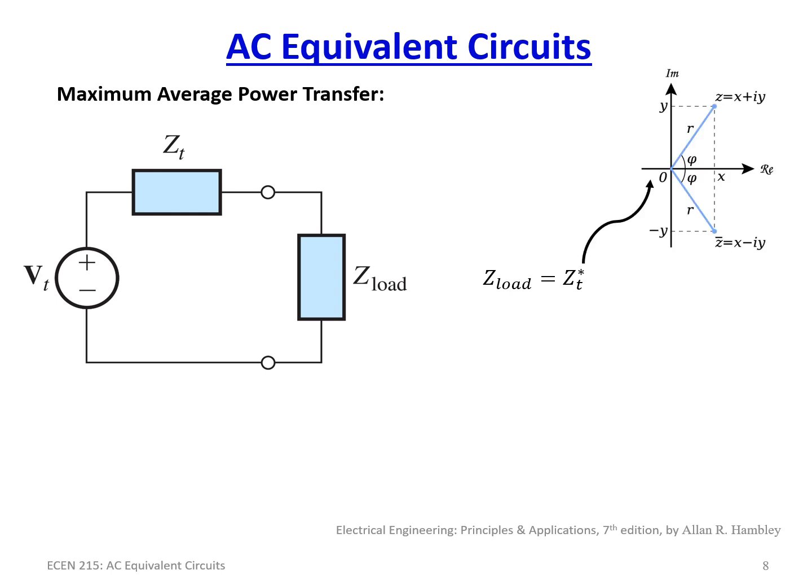And just as a refresher, the conjugate is where you flip the sign of the imaginary term. So if ZT was 5 plus 6j ohms, then the conjugate would be 5 minus 6j ohms. It's the same real resistance, you're just flipping the imaginary component. It also flips the phase angle.